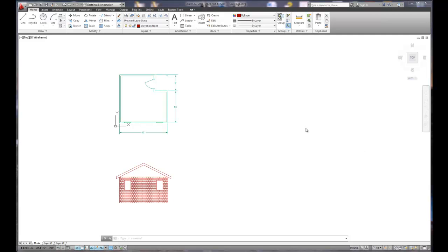So creating the elevation with the door, or the side elevation, the way we do that is very similar, except we're going to draw it projected off the side view. So again, we're going to change the layer to elevation side, and then we're going to project lines from the locations of the walls, and we can come across here to get the overall distance.